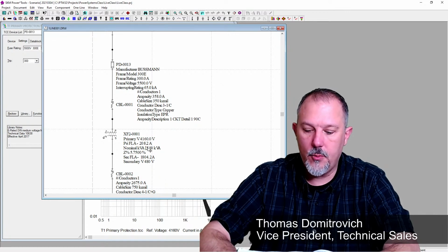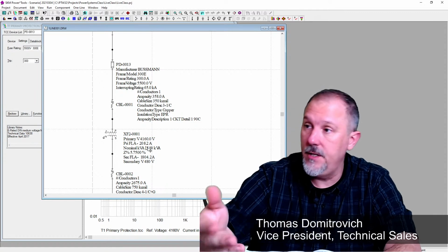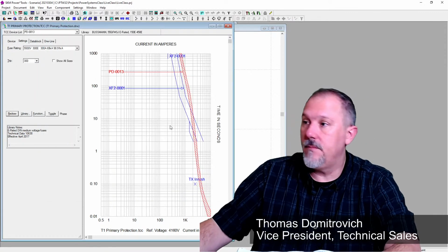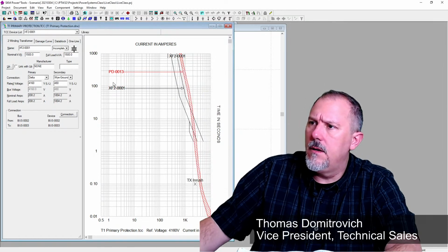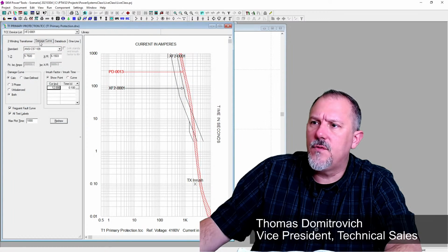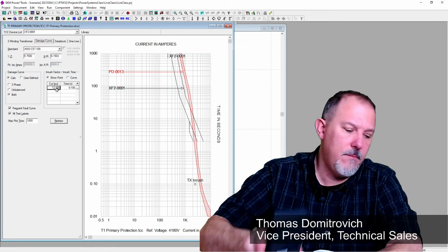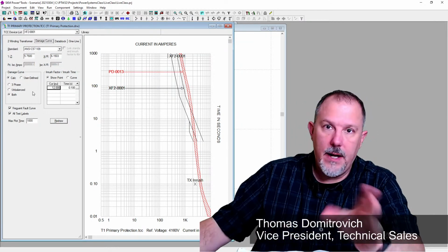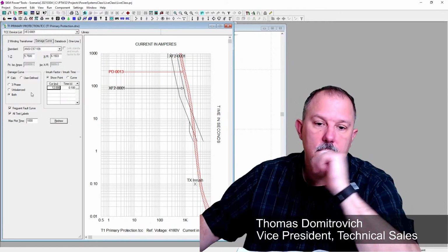208.2, and I'm going to do 1.25 because that's a good ballpark, is 260. I went to 300. And I plotted that. My inrush for that transformer, transformer damage, inrush is at 12 times. You know, I'm just going to leave it at 12. I would consult the manufacturer of the transformer to see, you know, is that right?